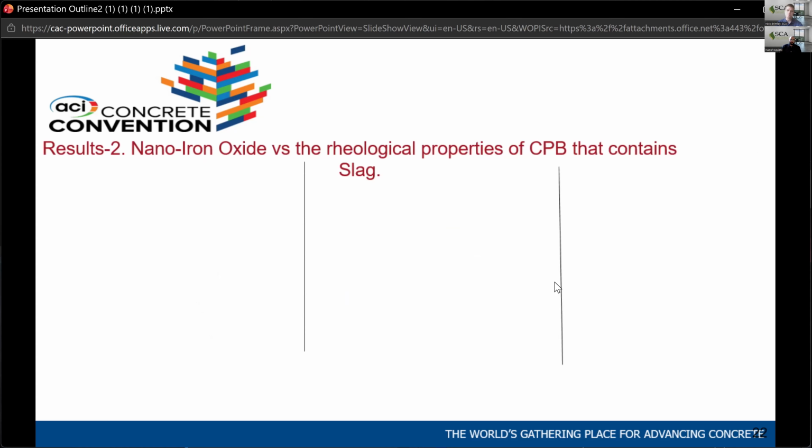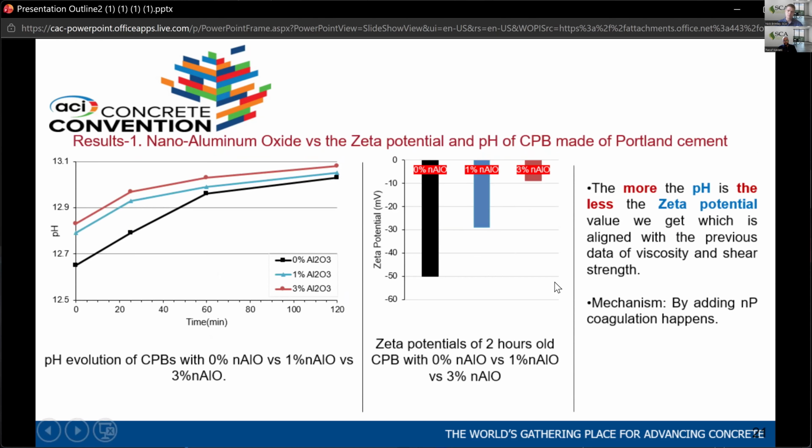Yeah, so when the coagulation happens, the ions are canceling each other basically. So they cancel each other, then fall down, and they're not hanging out in the emulsion, or whatever it becomes. That's why the zeta potential goes less.